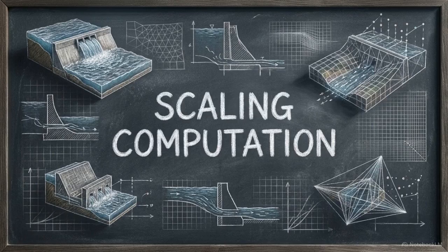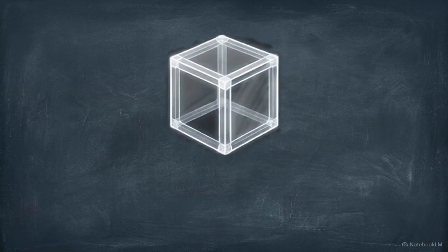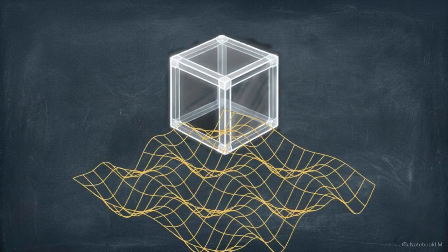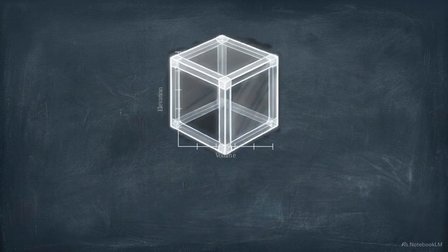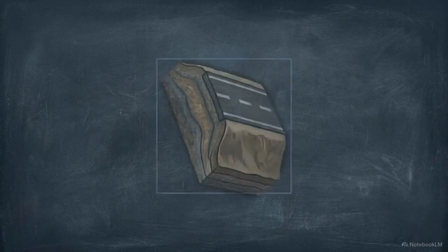solvers. HEC-RAS bypasses this limit using a proprietary technique called subgrid bathymetry. Engineers use large, efficient 50-meter computational cells. Behind the scenes, the software extracts a single elevation volume curve from the underlying 1-meter microtopography, feeding it into the larger cell's math. It retains perfect knowledge of the tiny gullies hidden inside.